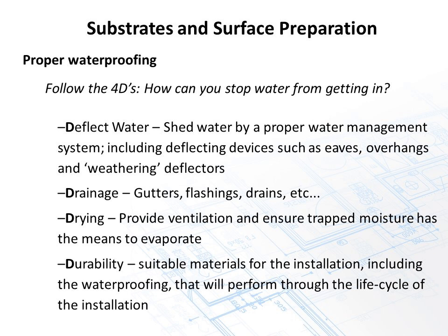One thing that's important when you're draining water off a deck, for instance, and it's going down the fascia of a suspended deck, where's the water going after that? Is it starting to discolor the front of the fascia? Maybe it's returning underneath that fascia and it's going to travel into an expensive finish ceiling. Take a good look at the drainage. Just getting water off the deck may not be enough.